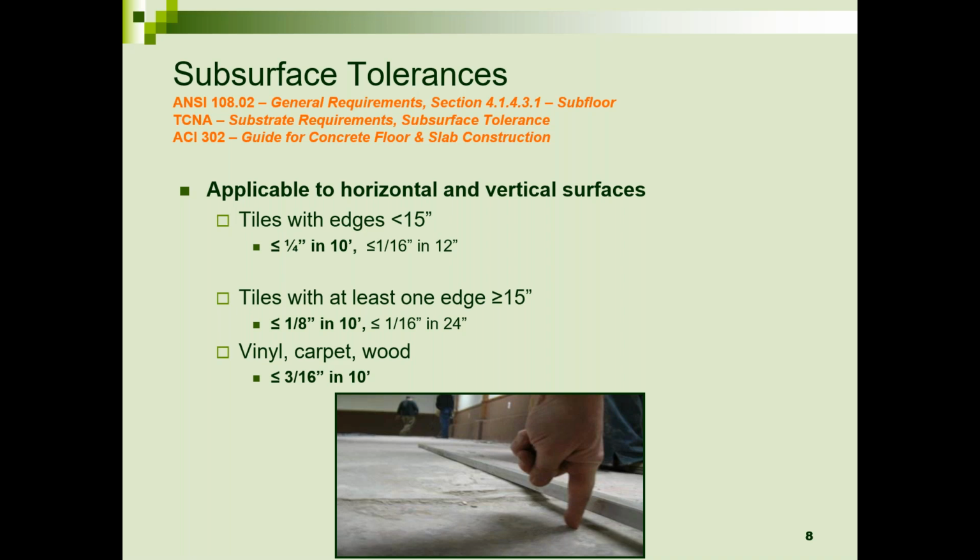But what's the reality if we're talking new concrete? Typically on a commercial floor, the best you're going to see is about 1/4 inch in 10, maybe even worse. So really all your tile installations, whether they're new concrete or remediation on existing concrete, you're probably going to have to do some flattening of that surface before you install any tile setting material. Membrane, mortar, or tile needs a flat floor to have the correct installation.